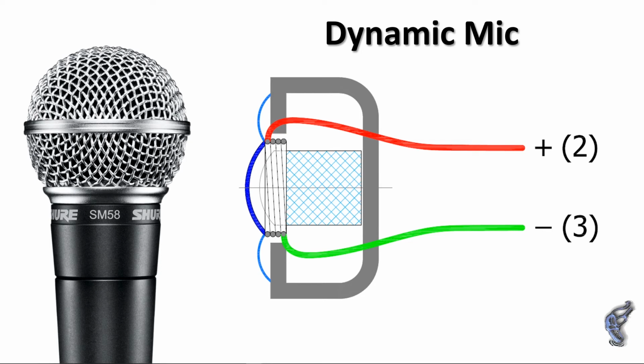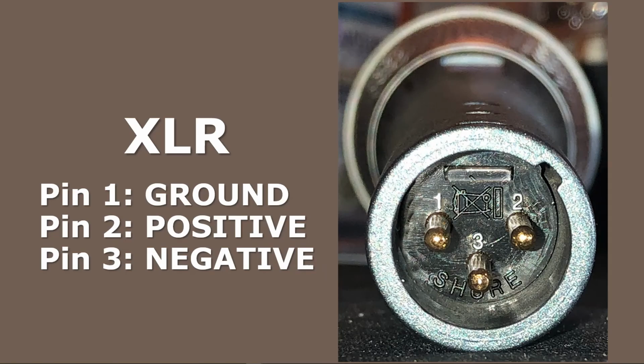As sound waves strike that diaphragm, it wiggles back and forth. That coil of wire goes for a free ride in that magnetic air gap. God's laws of physics says that whenever that condition exists, an electrical signal will be induced to flow in that wire. The 2 ends of that long piece of wire ultimately connect to pins 2 and 3 of an XLR connector built into the housing of the microphone. In a nutshell, that is how the dynamic microphone converts the acoustical energy striking the diaphragm into an electrical signal.